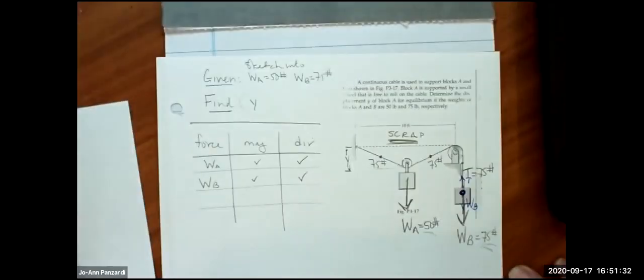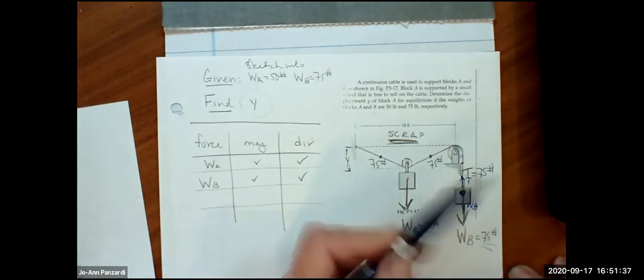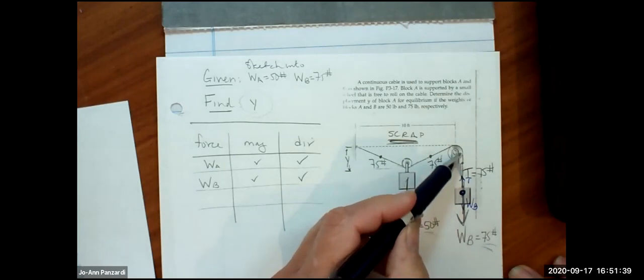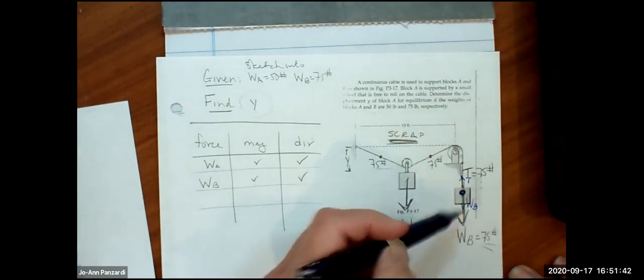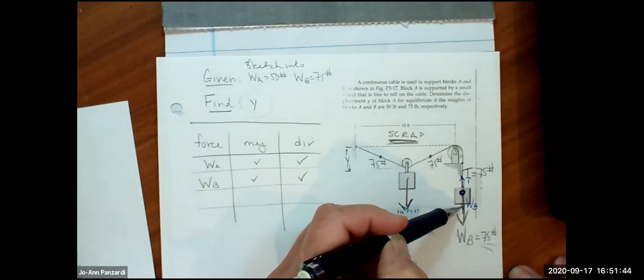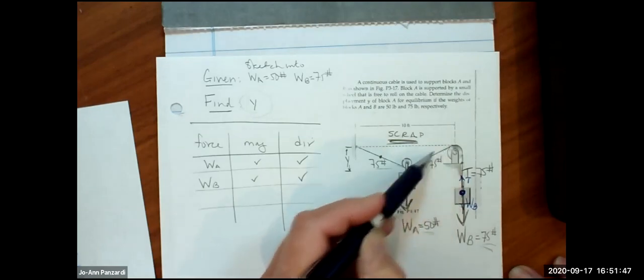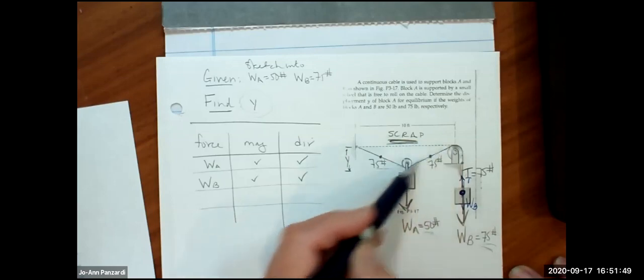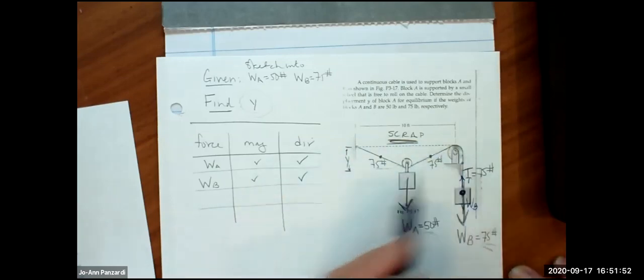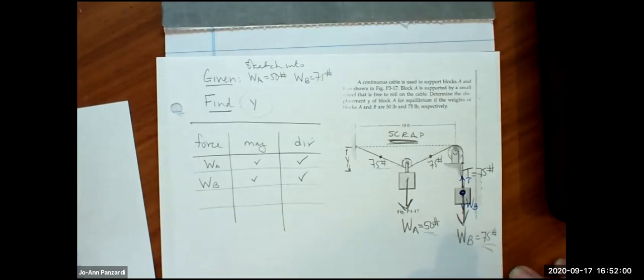Pretty awesome. The whole problem has been simplified because we understand two rules. One, if a cable's holding the weight, the tension in the cable is equal to the weight. We also know now that whenever there's a continuous cable, the same cable throughout, the load in it is the same. Joanne, it does change though, right? If it's two different ropes or two different cables. That's correct. If I had a pin or a ring and there was a cable here and a cable here, this is T1 and this is T2 because they're different cables.